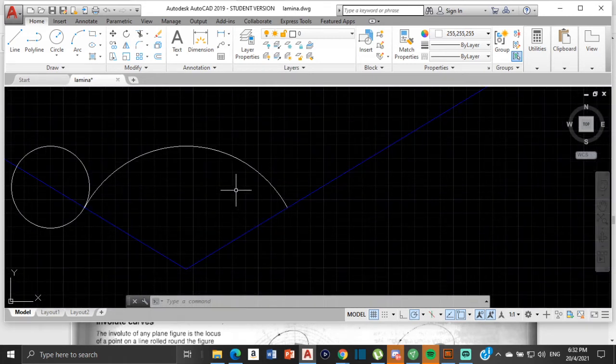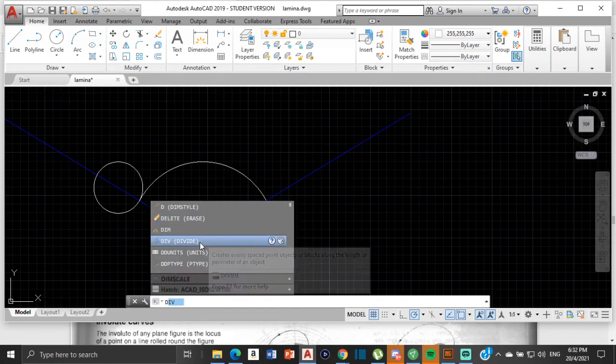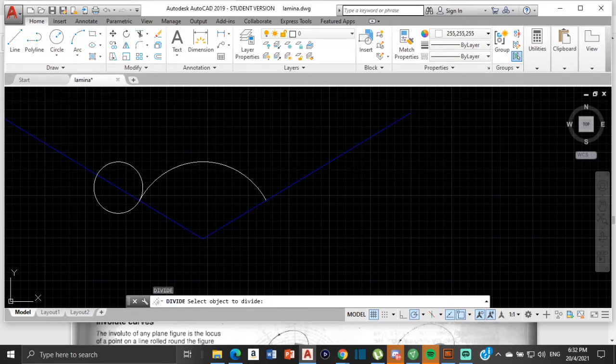Alright, so now here's what we're going to do. I'm going to type divide, and I'm going to click on this arc, and I'm going to type 12, enter.